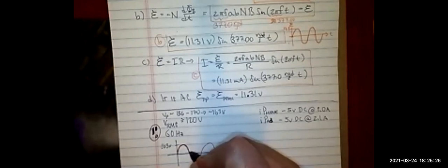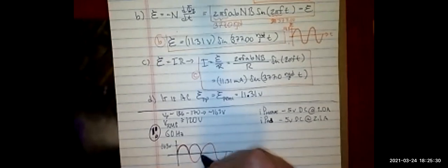So it got to keep that. But then it turned the negative upside down, so it got to keep that. Then it turned the positive up the regular way, so it got to keep that. And then it turned the negative upside down, so it got to keep that as well. So if you just did that, then you'd get basically a signal that was 163 volts and would look like this. That's not very good, right? You don't really want that.